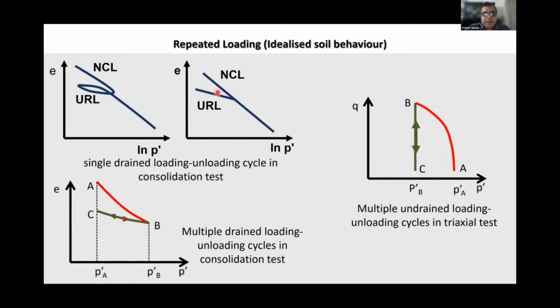Thanks. So if you look at the unloading reloading line, both Mohr-Coulomb and the Cam Clay family of models will tell you that no matter how many millions of times you go on this line, you'll just retrace this path every time. The same thing happens when you do multiple loading and unloading, so it's just a replicate of that figure.